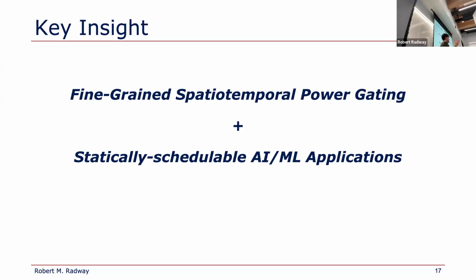So if we could actually turn on and off the components of our system such that we're only having the memory that's actively being read on when it's required, then that minimizes our total energy. It's actually very hard to do. So this requires both circuit implementation details, right? How we actually do this power gating, plus compiler tricks, right? We need to be able to think about turning on and off components of our system in our compiler.